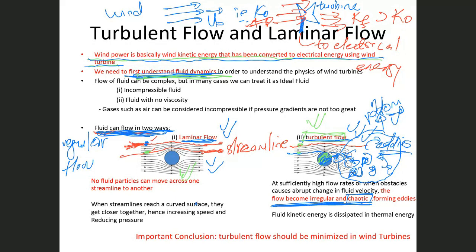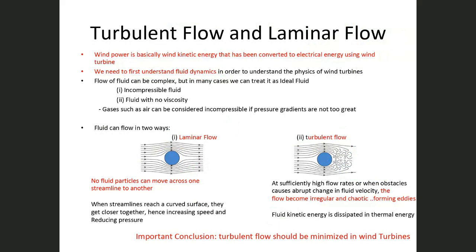Initially, we had the fluid moving at a particular velocity, which means it has particular kinetic energy. After reaching, for example, an obstacle, it becomes chaotic. In other words, it is slowed down in the direction towards the right, because some of the kinetic energy is now used, for example, to interact with other particles and move backward in a chaotic way.